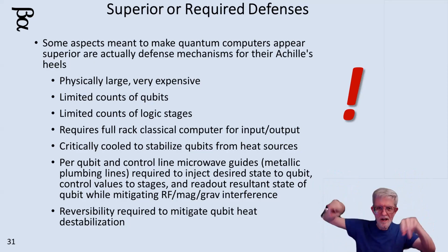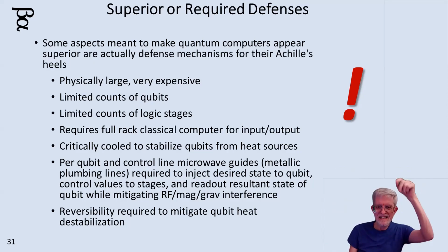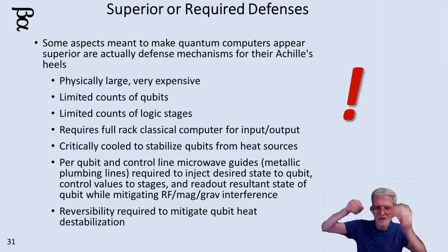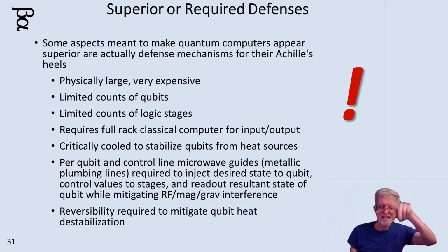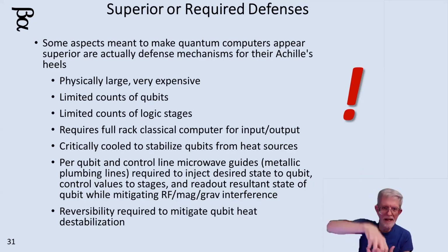I actually did a deep dive on the plumbing that you see in a quantum computer, and what's with the curlicues, where the plumbing pipe comes down and it goes around and it goes down further. Well, first of all, those aren't plumbing pipes. Those are radio frequency waveguides, and inside them, to isolate the waves, the photons, from being interfered with by the heated metal of the conduits of the pipes, is PTFE tubes, Teflon tubes. And the Teflon, when it gets really cold, has a different expansion, contraction than does the metal tube. So the way they solve this is they'll either put a bend or they'll put a loop, a pigtail, in the individual line. So if you've got 1,000 qubits and you've got 2 control lines for each qubit, you've got 3,000 of those plumbing lines that you have to deal with.